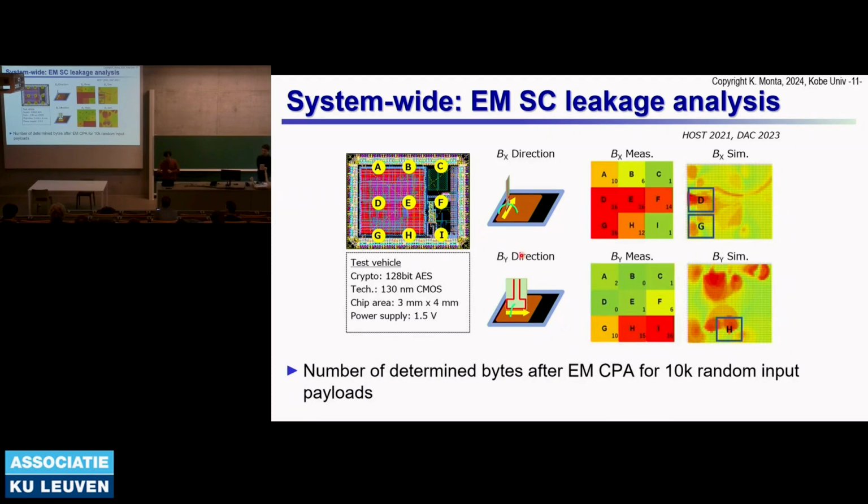And more, the core of our simulation is how accurately it models the power current dynamically consumed by the circuits. That can be straightforwardly connected with EM radiations, because you know that once the current flows through a metallic wire, there are magnetic radiations. And from the far field, you can see the electromagnetic waves. That can now be simulated. It's a connection of the circuit level simulation, power modeling, with the electromagnetic solvers. Now we can simulate. This is another type of system-wide analysis.